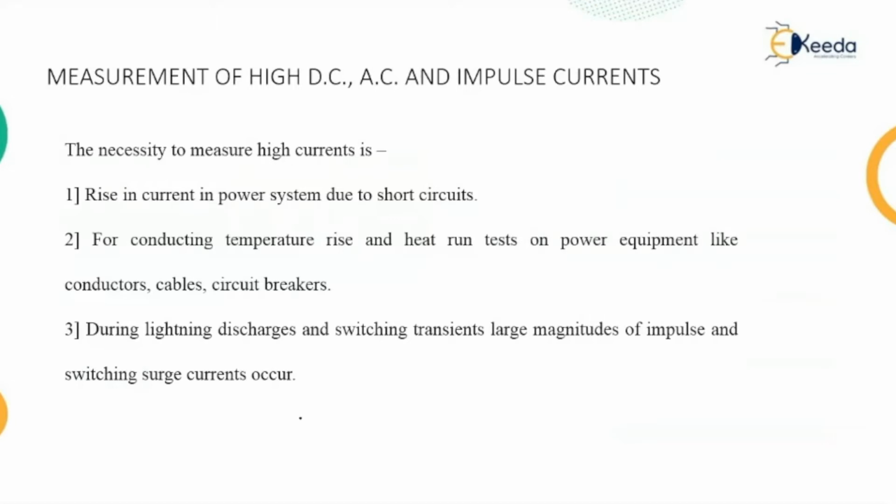But before that, let us understand the necessity of the measurement of high current. In case of a power system, if a short circuit occurs, maybe of any kind, that increases the current tremendously. The equipment placed on the power system should have a withstand capability for that current. So this rising current in the power system due to the short circuit has to be measured, or the withstandability of the equipment has to be calculated, and therefore there is a need for the measurement.